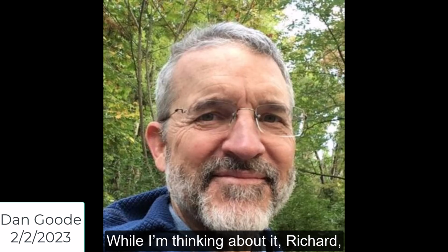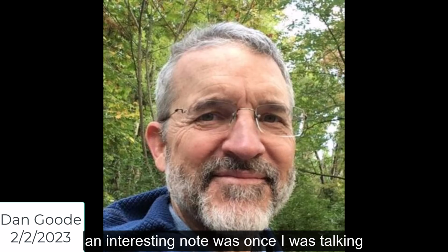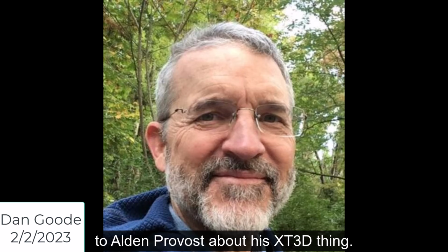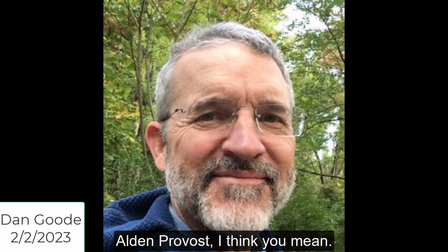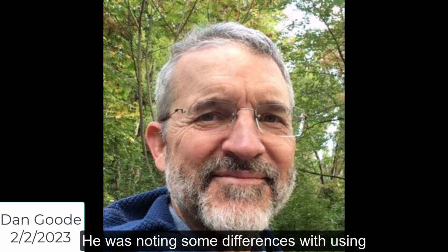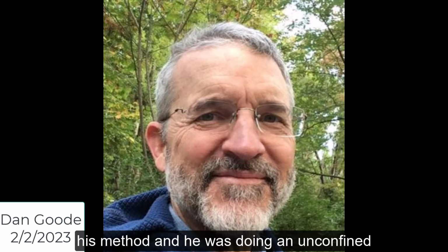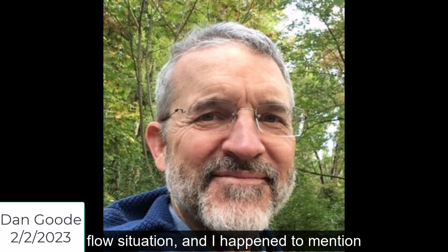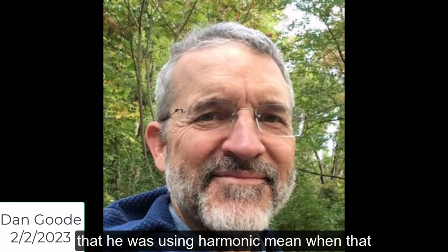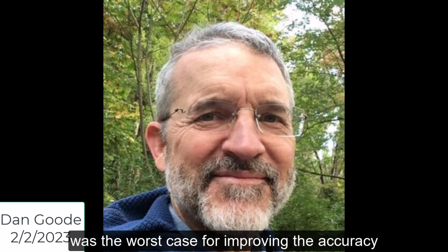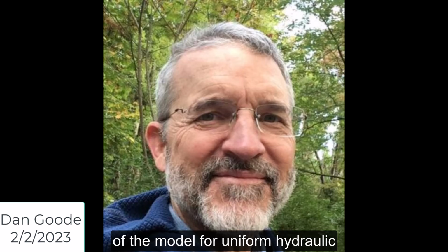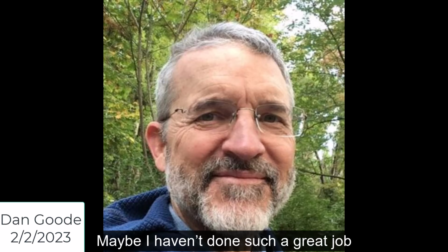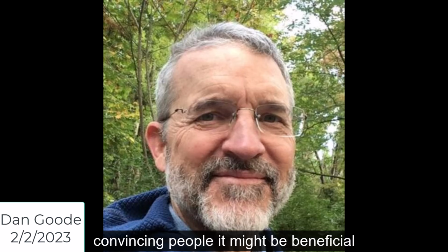So just while I'm thinking about it, Richard, an interesting note was once I was talking to Alden Provost about his XT3D thing. And he was noting some differences with using his method, and he was doing an unconfined flow situation, and I just happened to mention to him that he was using harmonic means, and that was the worst case if you're looking at improving the accuracy of the model. For a uniform hydraulic connectivity in an unconfined situation, that was the worst method to use, and he was unaware of that. So I think that overall this method is not widely used, and maybe I haven't done such a great job convincing people that it might be beneficial in some cases.